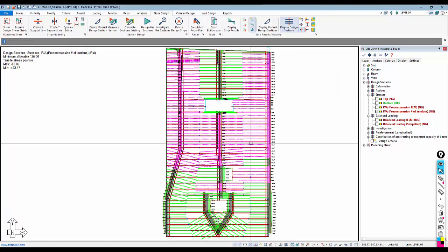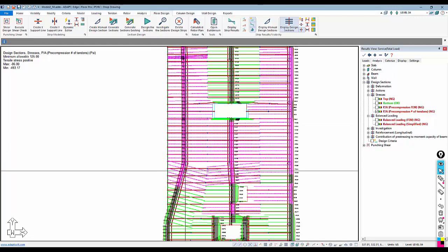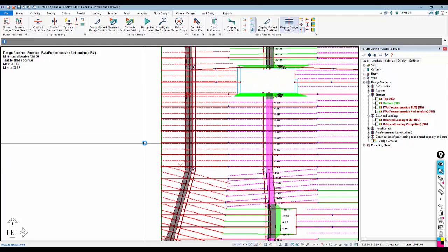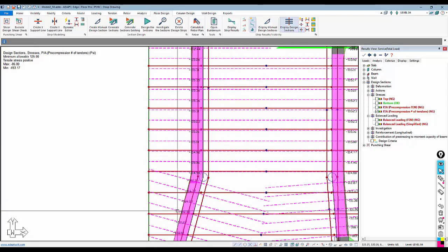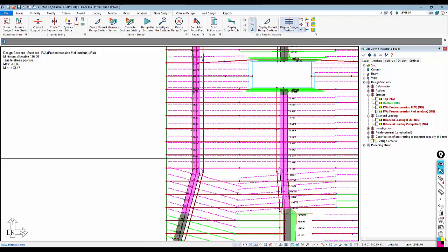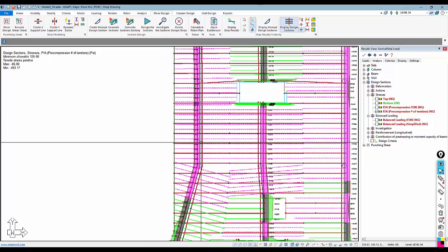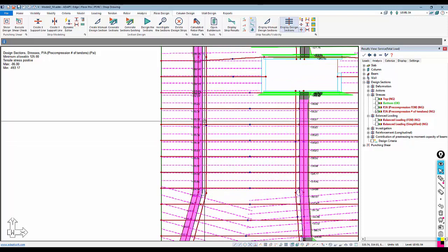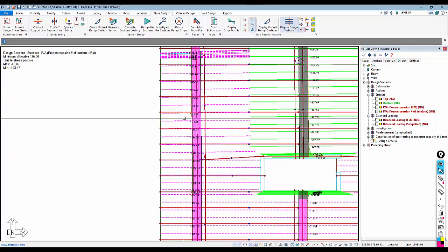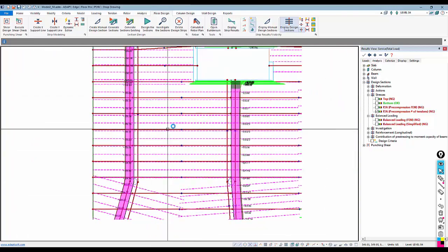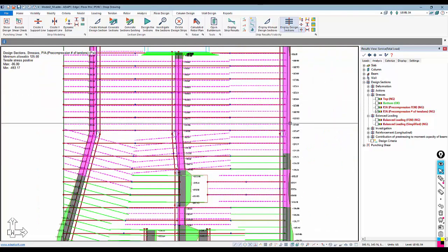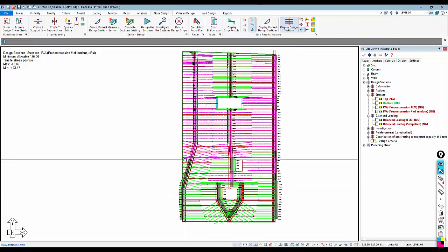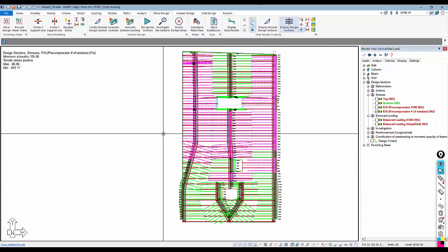If we go to the other direction, we have, again, areas where we have low precompression, and here we may simply need to increase the number of strands. So this is roughly 124, 125 into 115. In this case, because it's the banded direction, I don't have the same type of issue as in the other direction. So here I would probably just increase the tendons enough to where this area meets 125. I would do that for this strip, and also this strip. And then once you've made those changes, we could reanalyze, redesign, and recheck the conditions.